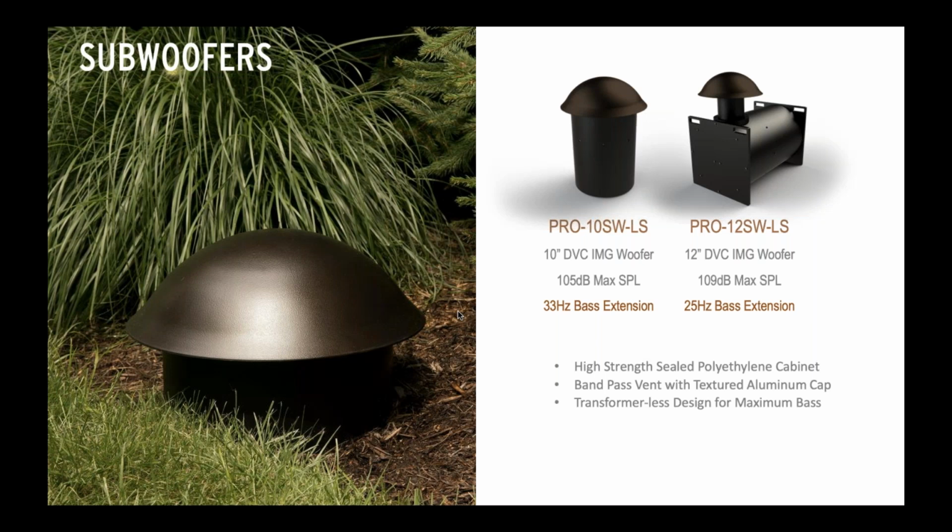So it's great info. Yeah, it's something we've done on commercial subwoofers. We have our commercial surface mount speakers. We have an 8-inch subwoofer product that is actually a dual voice coil. And again, depending on how you wire it up or which position the switch is in on the front, you're either using both of those voice coils in series or in parallel.